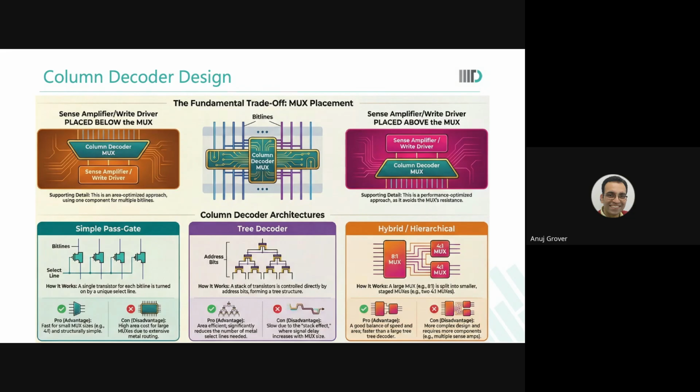And now in that short circuit path, you're not able to take this internal node to 0, because this is a kind of potential divider forming, a potential divider from VDD of port A to ground of port B. Because on port A the same word line was on, and the precharge for only this adjacent cell was turned off. The precharge for the unselected column of port A was on. If I had blanket precharged off, then this path would not have existed.